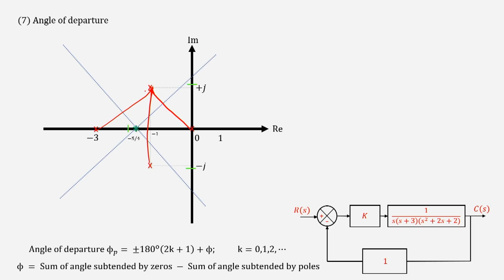That is the idea that we will use. Now, what is the angle that is subtended at a point very near to this point? The angle will be exactly this angle only. A little bit here and there maybe, but not much, because the point that I am looking for is exactly near this open loop pole. So, you subtend the angles that you get from these points, call them some angle. So, this is say phi 1, phi 2 and phi 3. These 3 open loop poles subtend minus phi 1, minus phi 2 and minus phi 3.